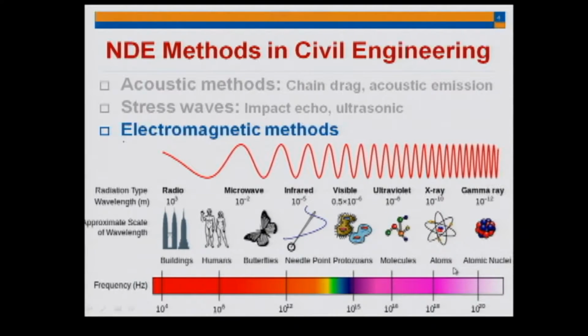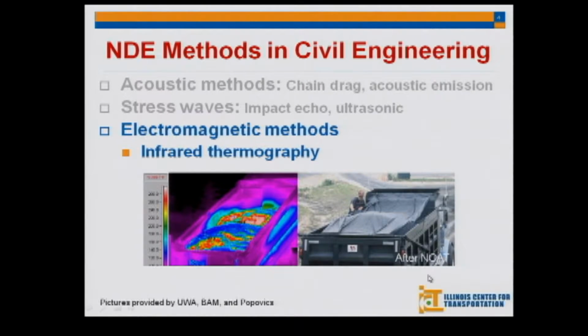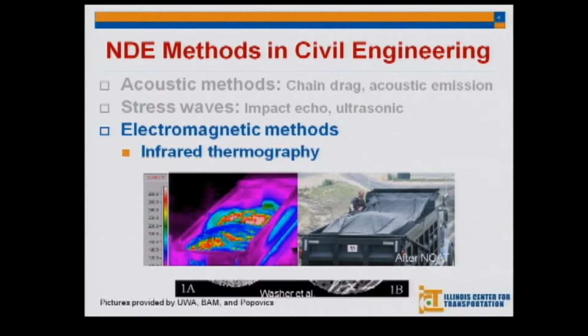To give you some examples of what we use in asphalt concrete, there is the infrared. The infrared is used sometimes to detect segregation in the asphalt concrete. The way it works is that if you have different materials, or materials that are cooler than the others, then you're going to end up with some segregation when you put it in the field. So you can detect this change in temperature during the loading of the asphalt concrete on the truck, which you cannot see, of course, and you're going to expect that you may have some problems when you place it and you pave it.